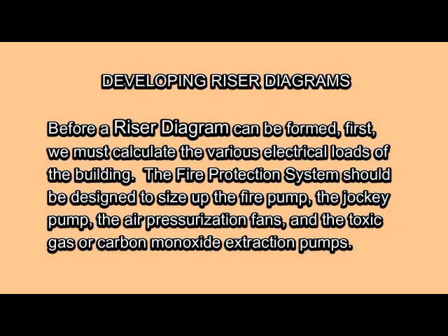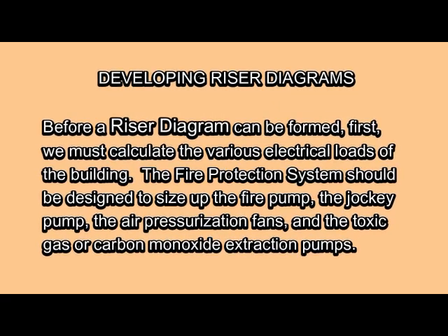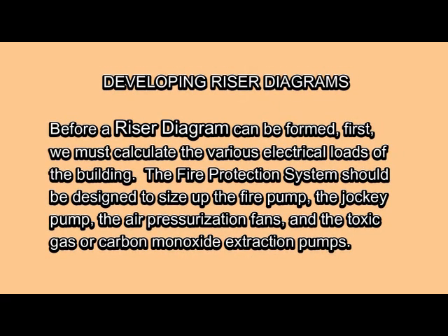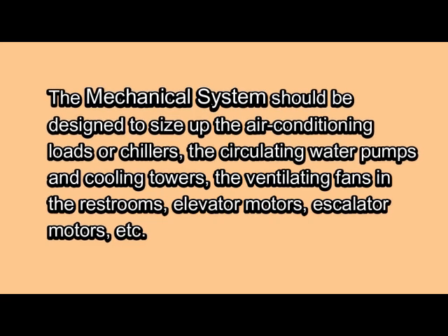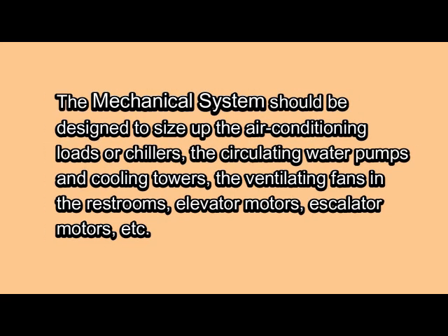Developing riser diagrams. Before a riser diagram can be formed, first, we must calculate the various electrical loads of the building. The fire protection system should be designed to size up the fire pump, the jockey pump, the air pressurization fans, and the toxic gas or carbon monoxide extraction pumps. The mechanical system should be designed to size up the air conditioning loads or chillers, the circulating water pumps and cooling towers, the ventilating fans in the restrooms, elevator motors, escalator motors, etc.